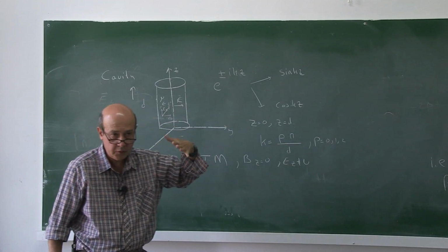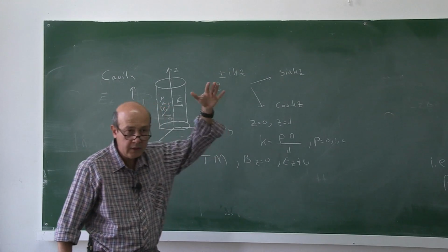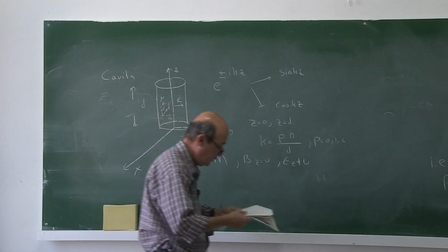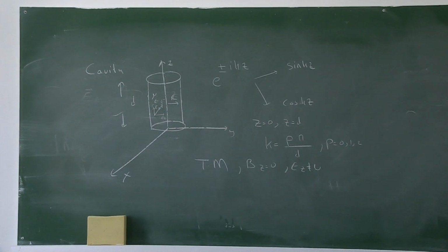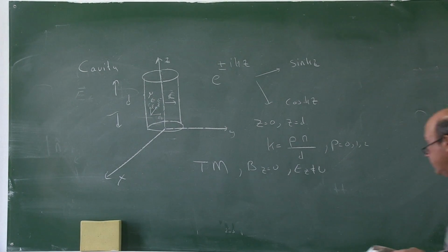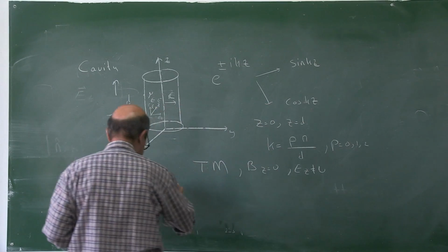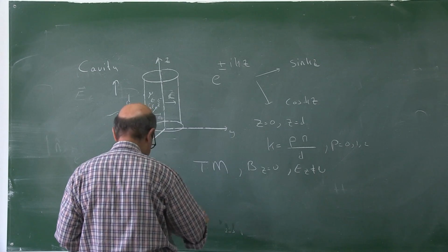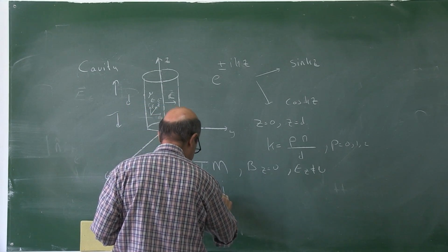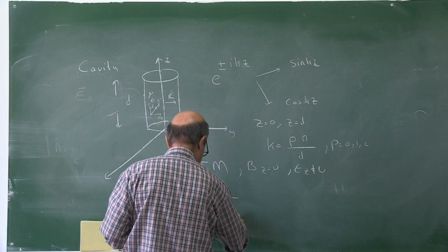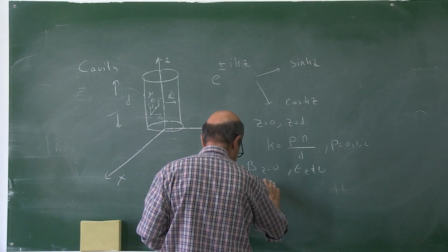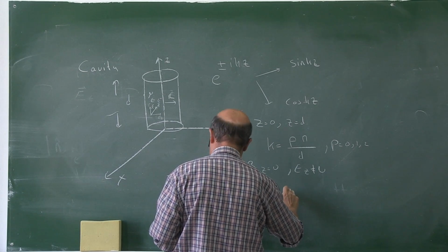The tangential component should also vanish at the up or down of the surface of the cylindrical cavity. So what is the E tangential? For a waveguide, E transverse, we actually derived, is i k over gamma squared times the gradient of the transverse Ez.